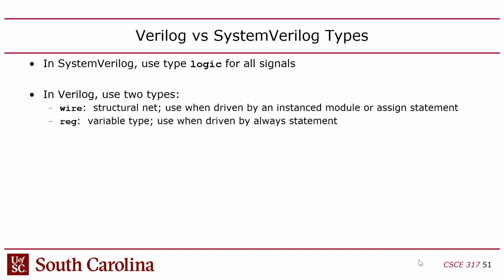Okay, and then finally, one last thing I want to mention, because this is relevant for Lab 3: one of the craziest things in Verilog that everyone hates is this notion that they have two different types of signals. Now, in Verilog, there's multiple data types. They have an integer data type, like Java. They have traditional data types. But those are usually for non-synthesizable code like test benches, right? When you're designing synthesizable code, you're generally only going to use a signal like a logic, right?